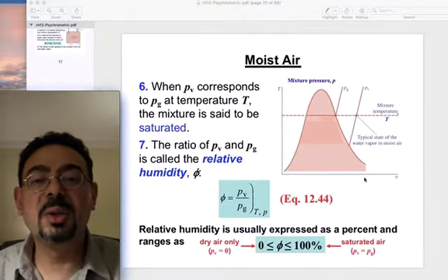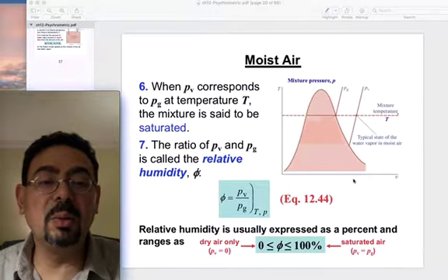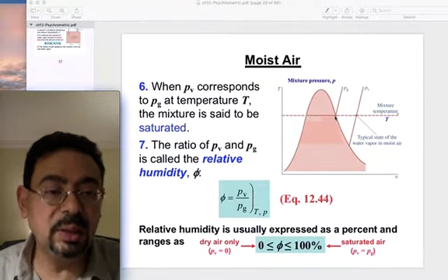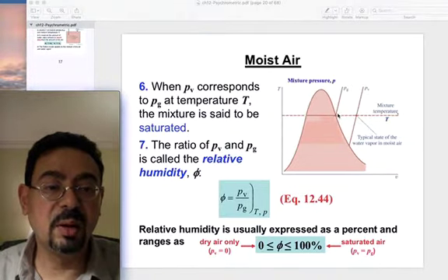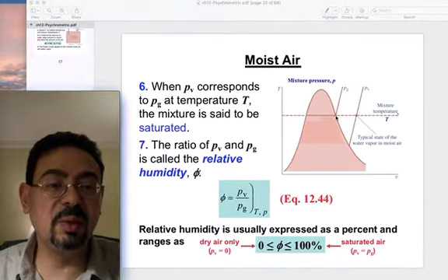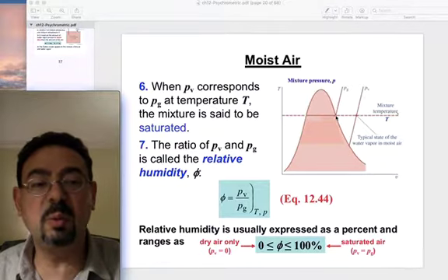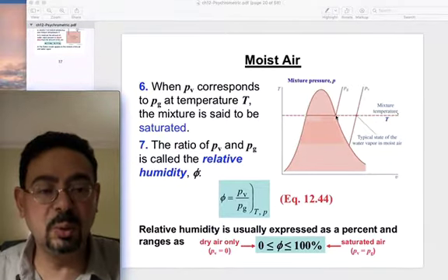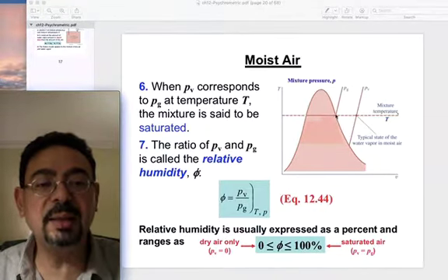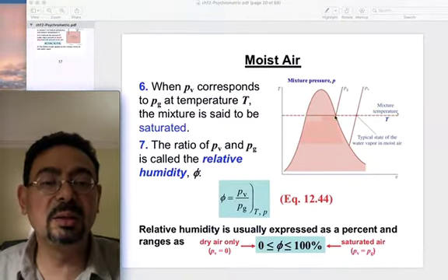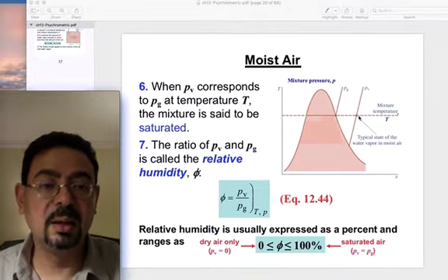Very good. So now if we are here, we would be saturated vapor, right? The air will have water vapor that is saturated vapor. Does this mean that if we are here, then everything is water vapor, and we will basically be breathing water vapor? No, right? There is still dry air. It's just that the water vapor in the air will be sitting over here. It will be sitting at its saturated pressure, right? Here it's superheated and has lower pressure than P saturation.